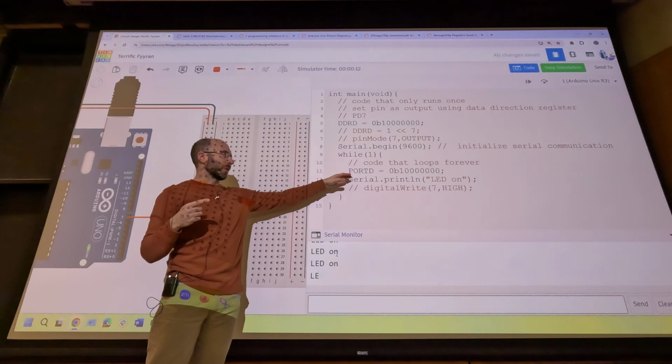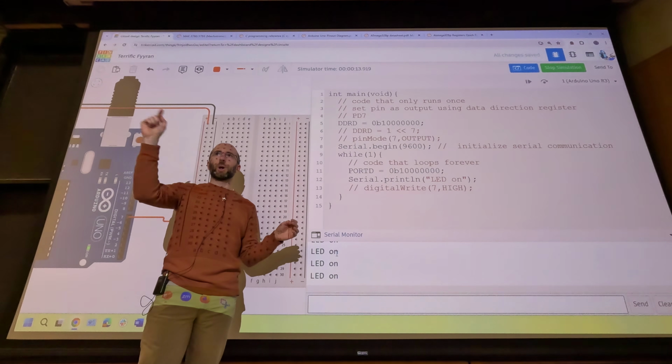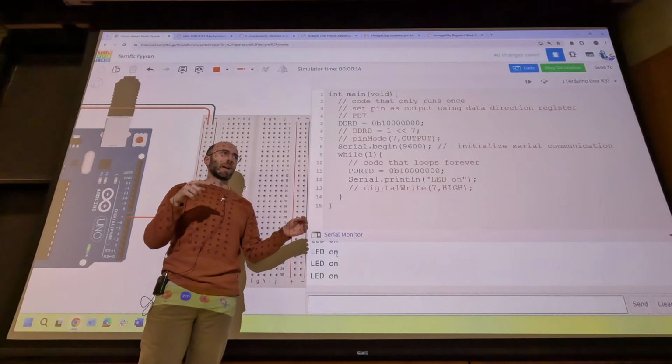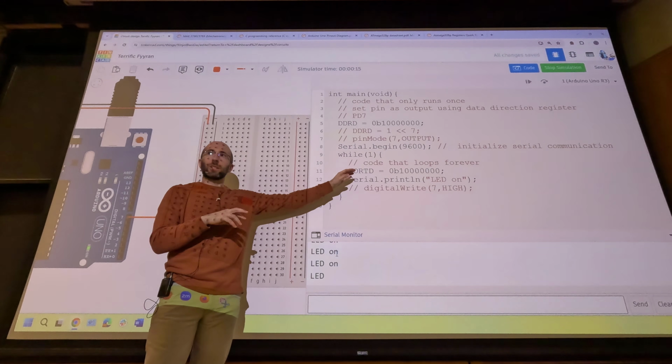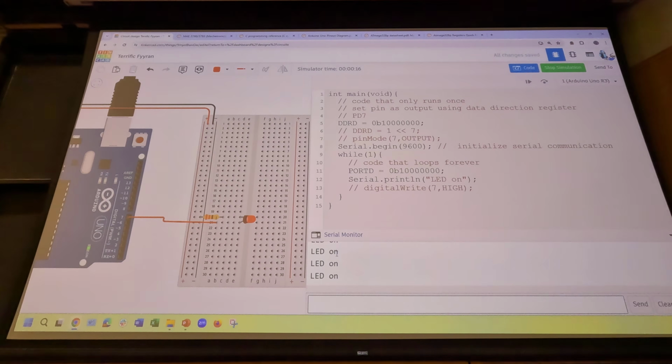And we'll see this, I don't think we'll get there today, but when we get to buttons next week, for example, you could print button pushed, button not pushed. And then you can say, okay, at least my code is detecting the button press even if my LED is not working. This is going to be really important as you get towards more complicated stuff and building the robot with multiple sensors and outputs.